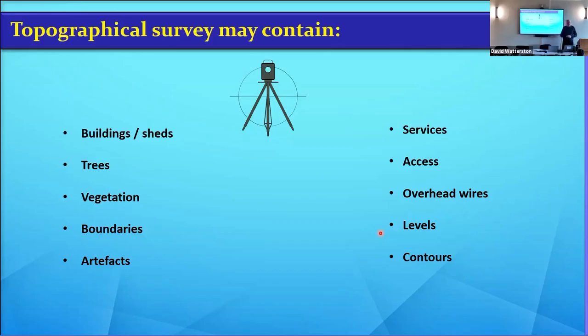And a level grid is set distances between the level from the furthest other level. So if they say, do you want a 5-meter level grid or a 10-meter level grid? What they're actually saying is, between one level point and the next level point will be no more than 5 or 10 meters. All right, so they're not talking about the line work on the drawing, they're talking about a level grid.